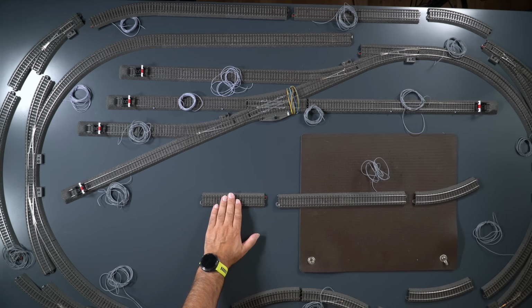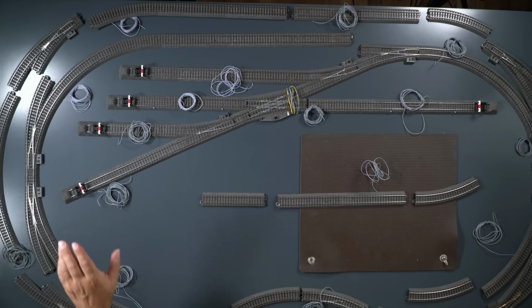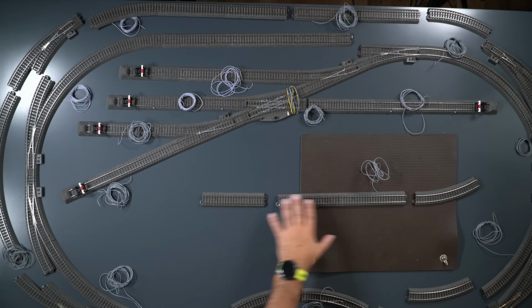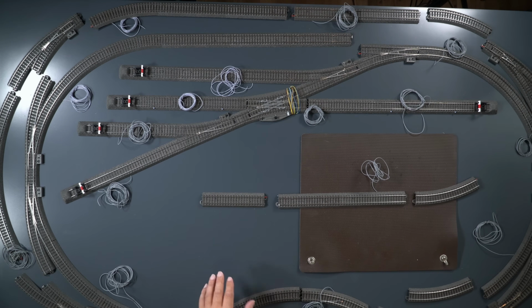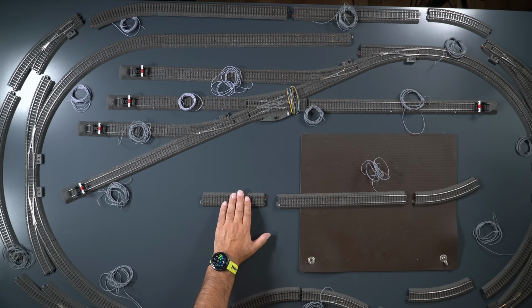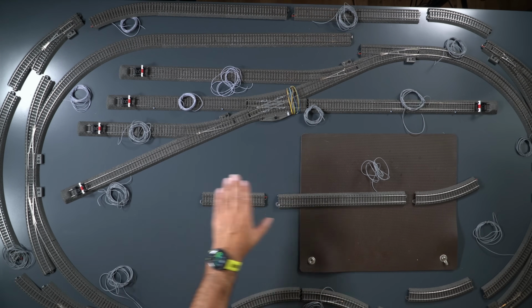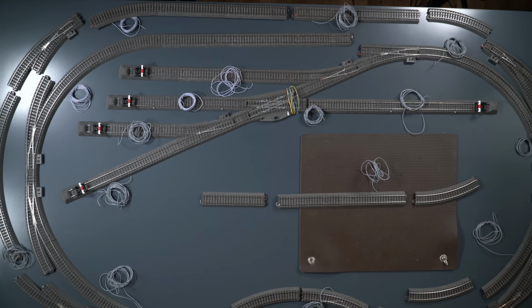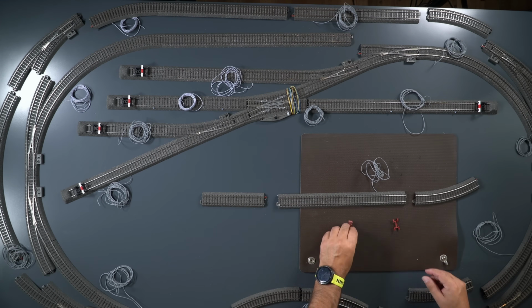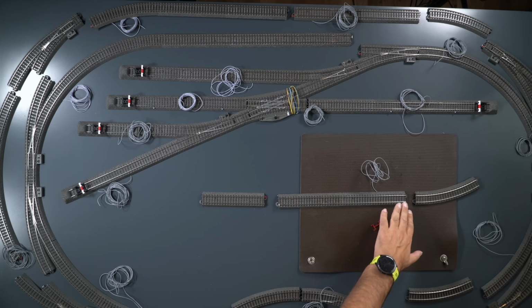And the first area is, of course, the so-called transition area, because there are differences between the railway and the power supply in the braking area, and to prevent a short circuit, I naturally need this transition track here, which essentially transfers the power from the normal supply to the braking area. And all these 3 rails that I have now pulled out here from the signal area must now be electrically isolated from the rest of the layout in terms of the center conductor. In this case, we again use our insulators, and on each track, both at the front and back, the tab responsible for the center conductor must be fitted with an insulating shoe so that no current can flow through here anymore.